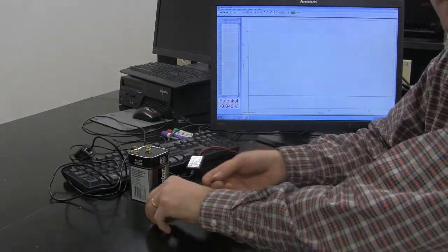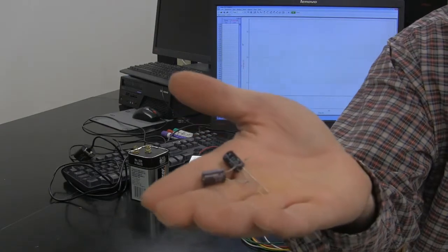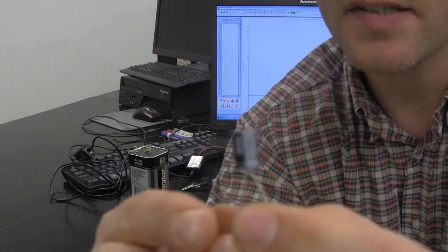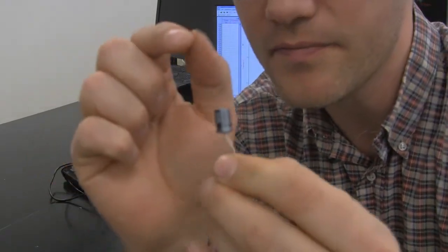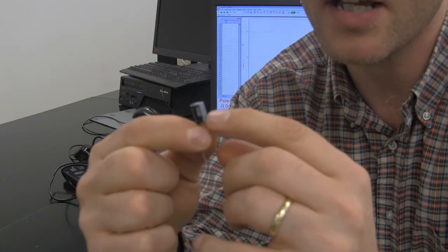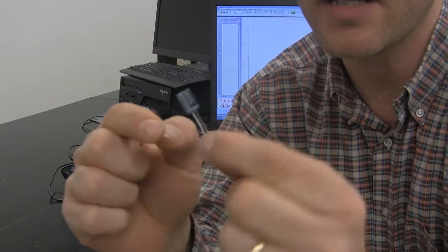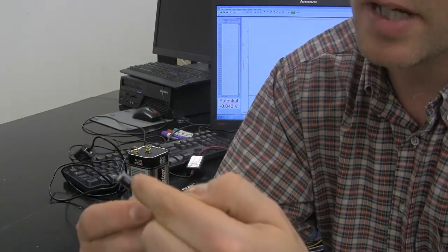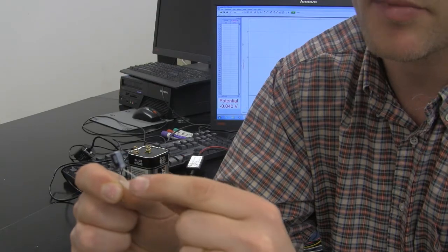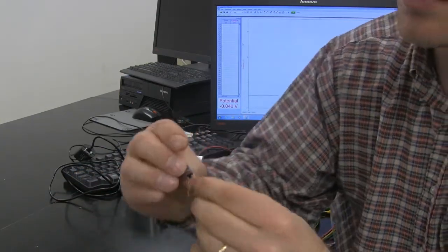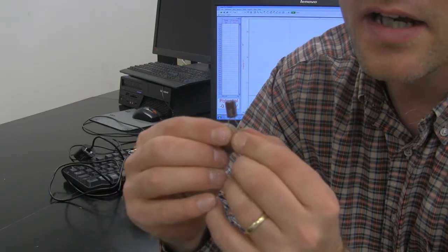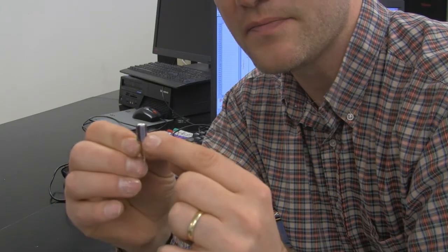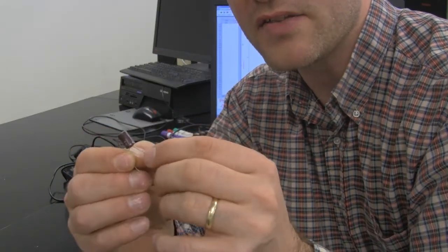And last of all, our capacitors. And these are the capacitors. And you see on one side of the capacitor there is this sort of a dashed line. I don't know if we can focus on that, but it's a dashed line that indicates that this is the negative side. The other side is just plain. That's where the positive side is. So it's sort of a strip with a little negative sign, a little bubble almost. That's the negative side of the capacitor. The same with this one. There's a little strip there indicating the negative side of the capacitor. The other side is just blank. So this terminal is negative.